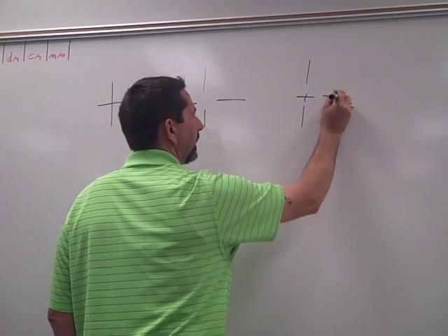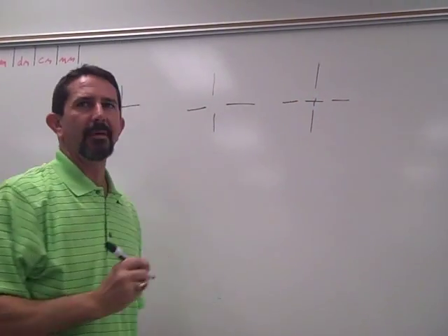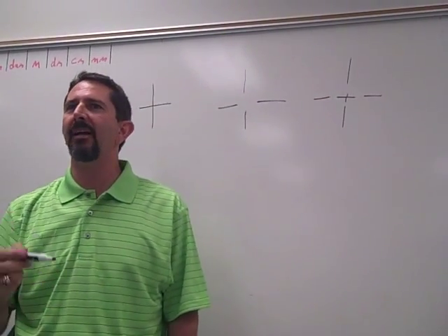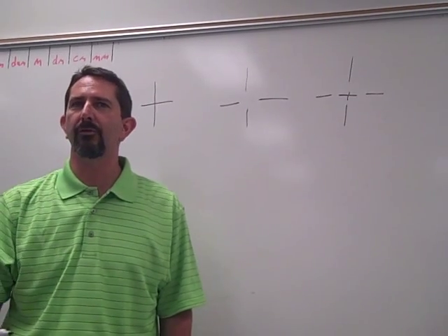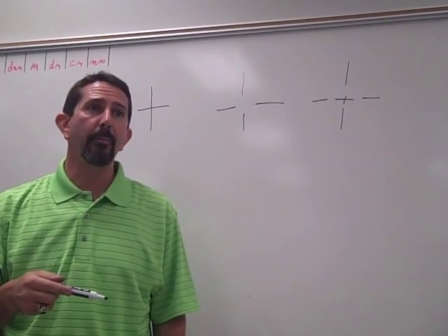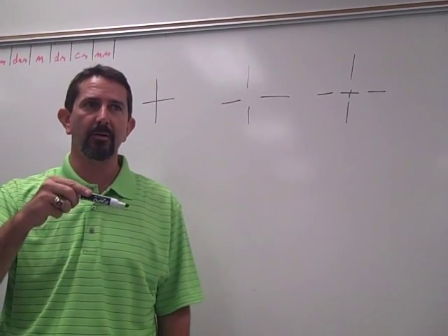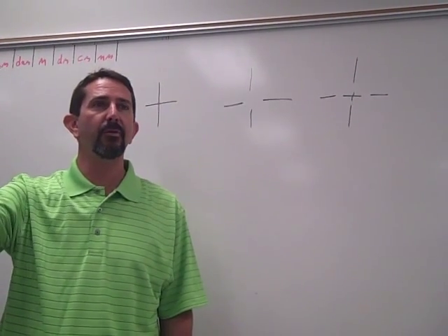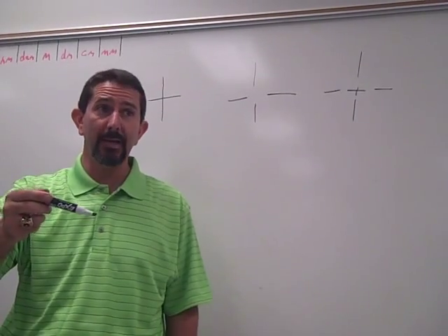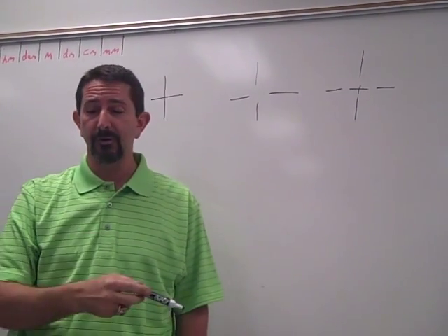This is a hidden fastener. It means the fastener is there, but you cannot see it from the front side view that you are looking at. This is quite common on an aircraft to see hidden fasteners because they may be installed, but you not necessarily can see them from the view that you are putting in, or you may have to put them in, but it's not visible from the view you're looking at.